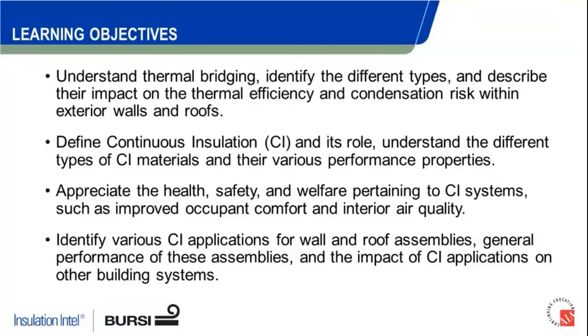of course, air barriers, vapor control, things like that, that when you start introducing CI to a system, it allows you to do additional things beyond just the thermal aspect. Talk about some of the health, safety, and welfare aspects relating to CI systems, again around how we're changing the temperature profile and the vapor profile of a wall system and how that can significantly reduce the risk of condensation within a wall system.